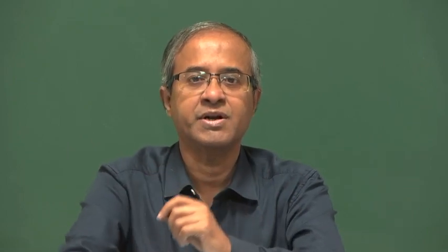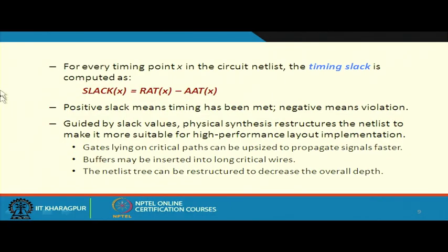There are paths which are geometrically you can see there is a path, but with respect to the signal value, the gates will work in such a way that the signal will never propagate along those long paths. So if you can identify the false paths a priori and remove them from your consideration, then your analysis can become much faster. This is one important point.